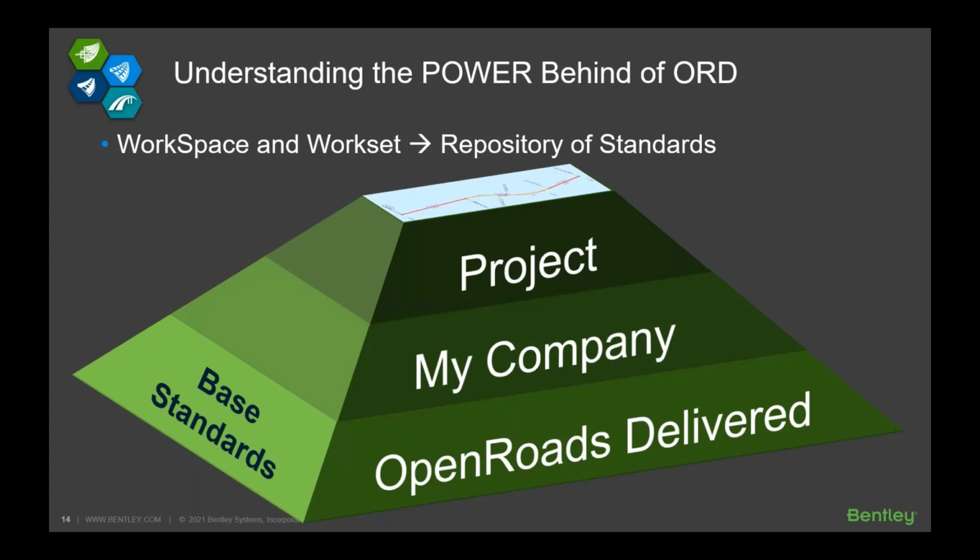So these workspaces are a repository of all standards that you may have in your project. It stores all your default CAD and, of course, civil design libraries, including your annotations, civil object styles, like your alignment styles, geometry styles, terrain styles, corridor styles, and, of course, your drawing sheet styles. When I say drawing sheet, these are your plan, profile, or cross sections.